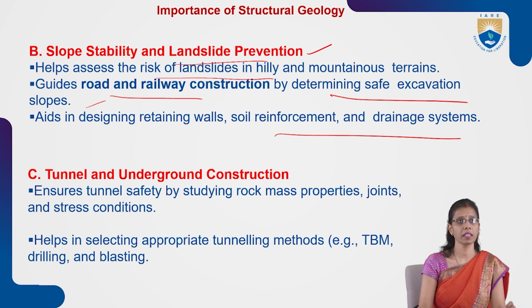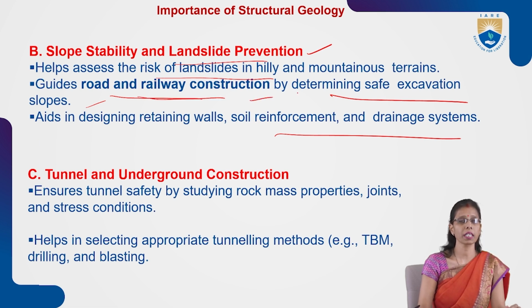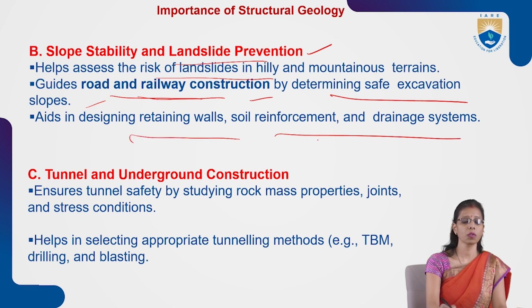So here, for slope stability and landslide prevention, it is very important to understand the structure of the geological features, because it will help us to assess the risk. In the future there may be a chance of failure, so it will help us to assess the risk on hilly mountainous terrains, and it will guide road and railway construction by determining the safe excavation slopes, and it aids in designing the retaining walls, soil reinforcement and the drainage system.